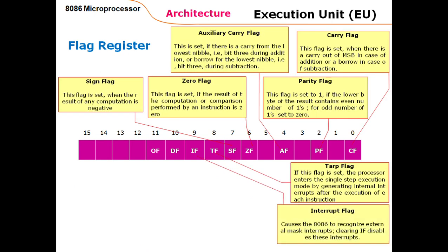Similarly, there is an interrupt flag. Interrupt flag causes the 8086 microprocessor to recognize external maskable interrupts. If we clear this interrupt flag, it will disable the external interrupts.